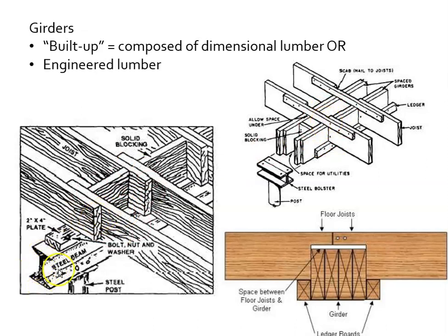So here we see a steel beam as the girder, wood plate on top of it, joists coming from each side of the foundation and crossing past one another. So you wouldn't make joists just meet and butt into each other. They would cross over each other and overlap some, and then we see the blocking coming in. This is pretty common.